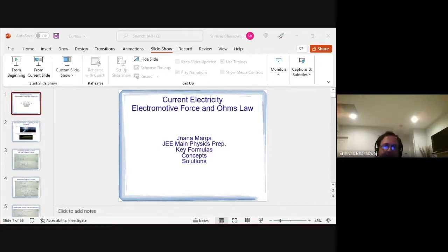So what is the open circuit voltage? Open circuit voltage is 10 volts. Why do they call it open circuit voltage? Because there's no current. At the time when you talk about the open circuit voltage, there's no current. But when you start supplying current, the battery itself will have a resistance, and some of the I will go through that r, through the internal resistance as well.